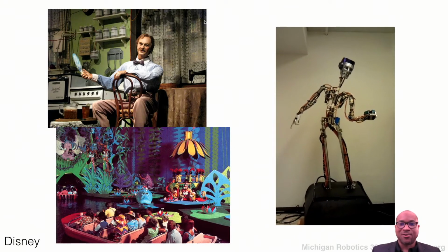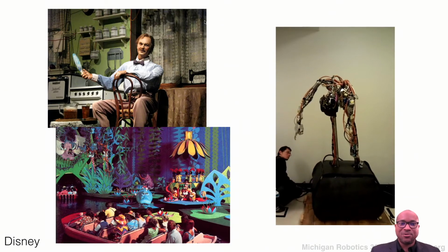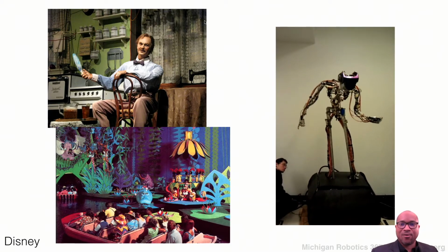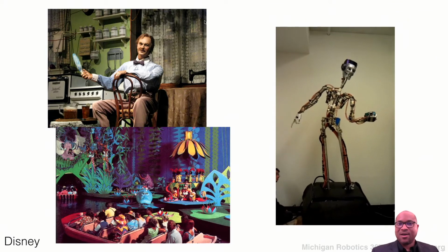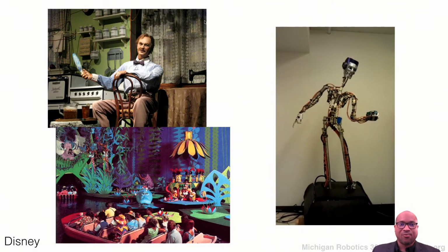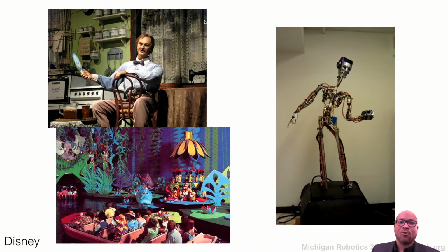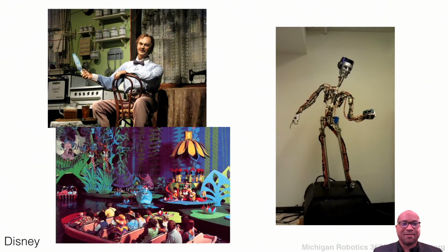And these robots aren't necessarily going to interact with anything. They're just going to do the same motions over and over again. Why bother doing closed loop control? Because you want prescribed choreography. That's more important. So open loop control makes a lot of sense, especially if you're going to do this at scale.